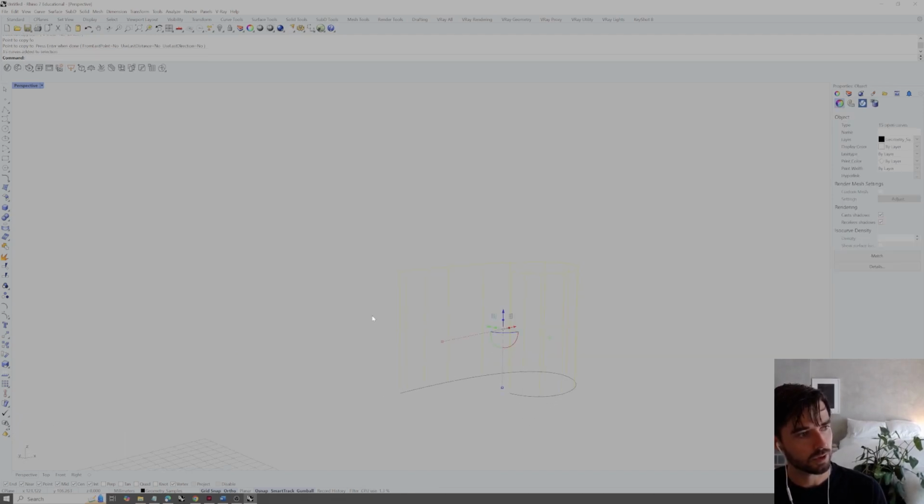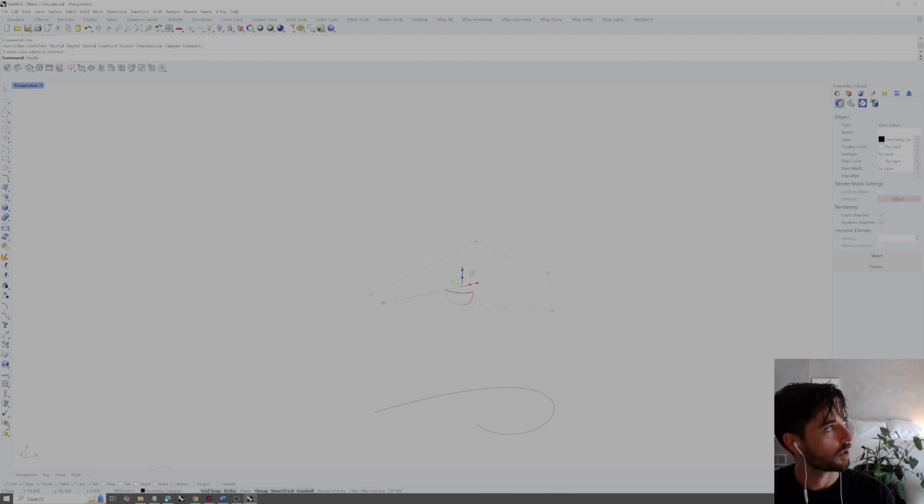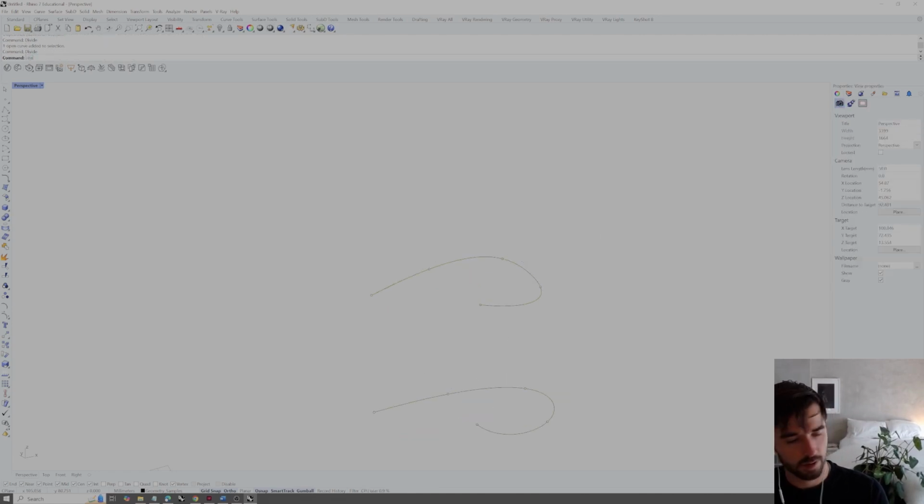of that extrusion. If we wanted to do this with 2 different curves but still connect them, so I'm going to just copy this one up, make an adjustment to it, this would be done with a lofted operation. So a loft is going to be defined by the connections drawn similarly between divisions on one curve. So if we just divide and divide again, and then draw the connections between these, very similar to the Bezier curve definition from a polyline.